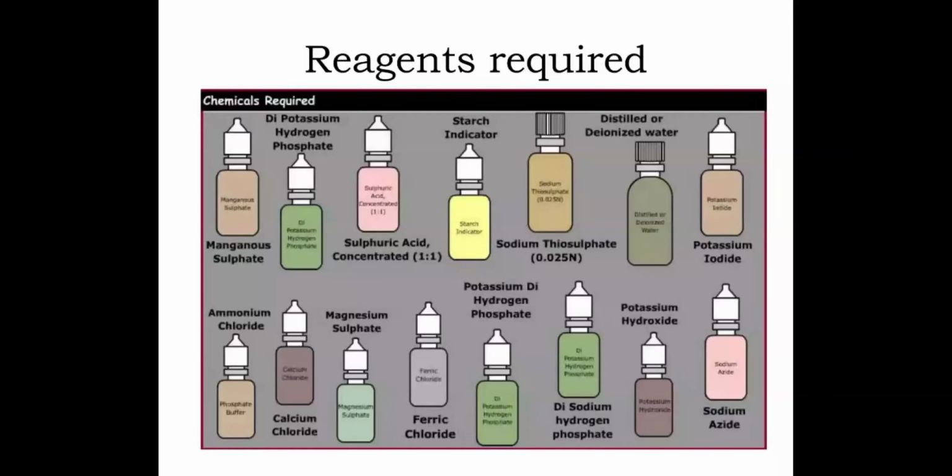These are the chemical agents, reagents required for this one, right? These are some sample collections. The BOD test can use a grab or composite sample, more preferred as it is representative of the waste stream over a period of time. The sample should be taken at a point of well mixed and proportional to the amount of the flow.